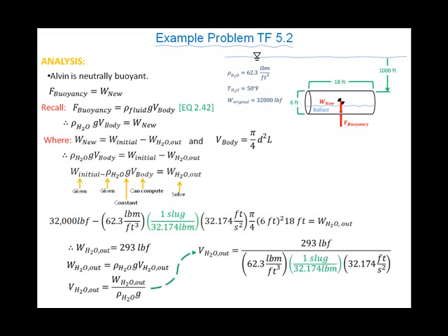And if I put in my values, again, note the conversion. I had to cancel out those pounds mass from density because I'm multiplying it by acceleration due to gravity in feet per second squared, and I want those pounds force to cancel out, and I want volume there in the denominator to come to the numerator to give us our volume. And what we get is that the volume of water I have to expel out is 4.703 cubic feet. And double underline answer, there you have it.